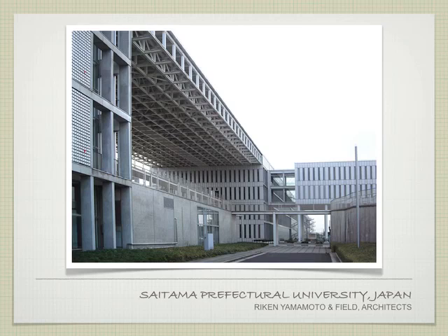And what they were able to do is they divided up those tubes on each floor and made them classrooms, right? So on the back half of each studio floor, there's 2 little classrooms, right? And those are the primary lateral loading support for the tower, right? They also went underneath and completely dug out the existing foundation, got rid of it, and poured a new raft-style foundation, which is giant. I forget off the top of my head what the spec was on how many cubic yards of concrete, but it's just an absurd amount of concrete under the building that provided an entirely new foundation for it. So they tied these tubes into that new foundation. Now the building's seismically stable, right?